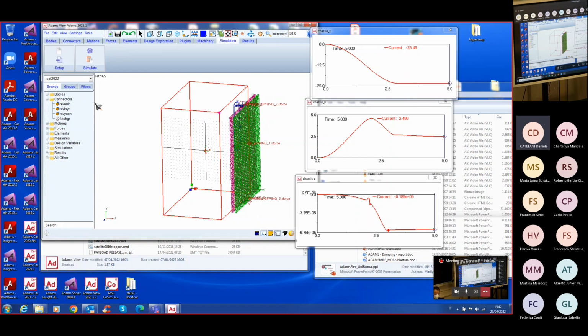So we need to create differential equations for doing it. In order to make things easy, I want to use only a proportional controller. So I monitor and control only displacement, not the velocity, not the integral of the displacement.